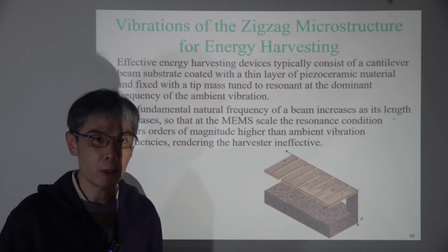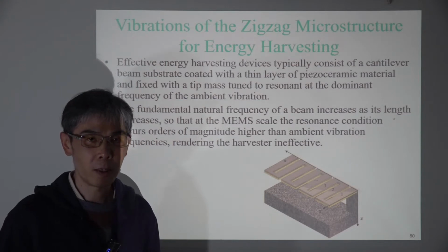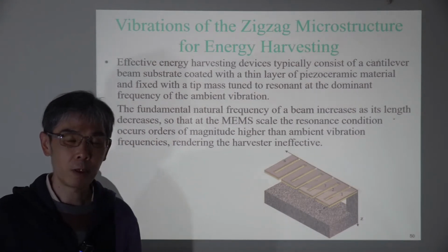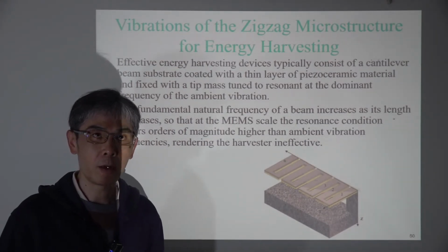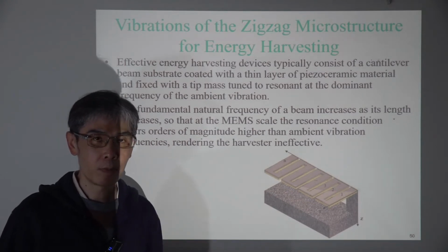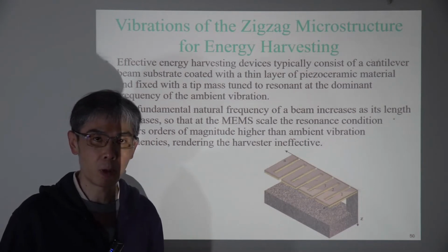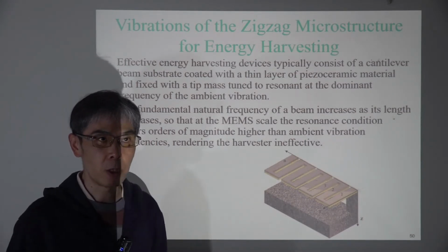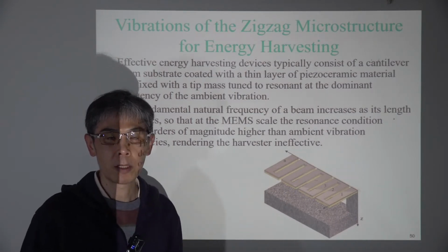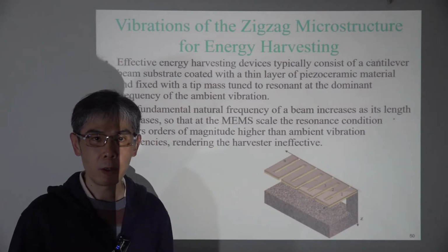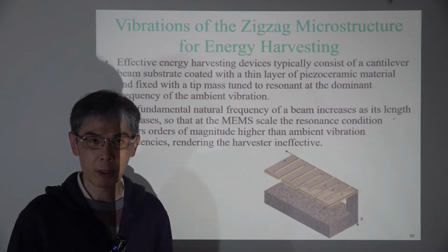Remember, we are talking about micro devices in this series of energy conversion devices. For a small micro device, because it's very small, the resonance frequency usually is in the kHz range or even megahertz range. Then the traditional micro devices are not suitable to convert the low frequency environmental vibrations.